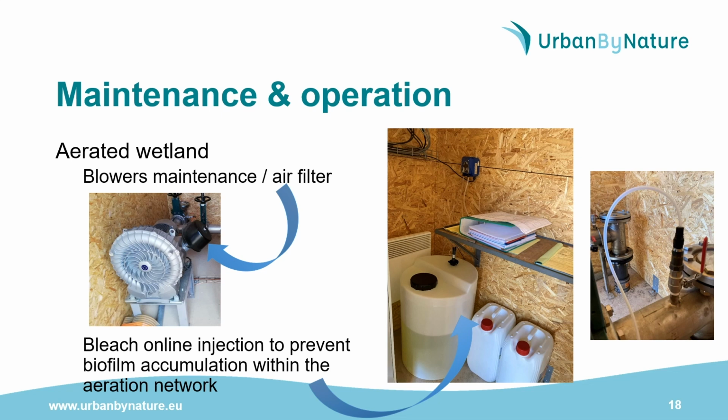This consists of changing the air filter of the blowers every 2 years, and also having a regular bleach online injection within the aeration networks in order to prevent biofilm accumulation that can grow within the aeration pipes. This consumption of bleach, which can be stored within the technical room, is really low and quite efficient.